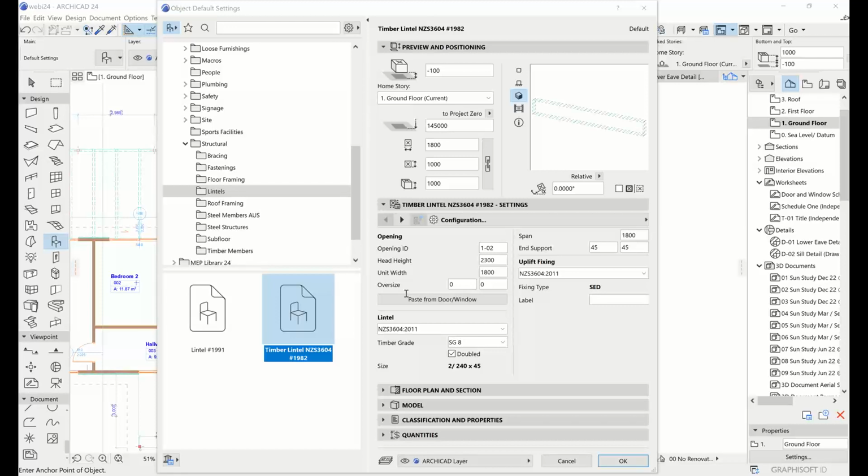So if you're doing renovations and you want a window to show in different statuses, you will just have to place two windows, one in each of your walls, and then make sure that the renovation settings are set up so that they show in the correct views. But yes, that does get quite tricky. Just because of the way that windows and doors work in ArchiCAD, and that they are sort of subcomponents of the walls themselves, it just won't let you do something like that, no.